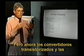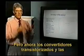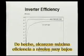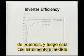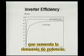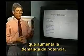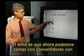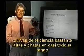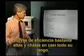But now we have transistorized-based inverters, and the efficiency curves are quite good. In fact, they actually peak in their efficiency at very low levels of power, and then slowly drop off in power as you increase the amount of power demanded. The point is that you can count on an inverter nowadays that has a fairly high and fairly flat efficiency curve over most of its range.